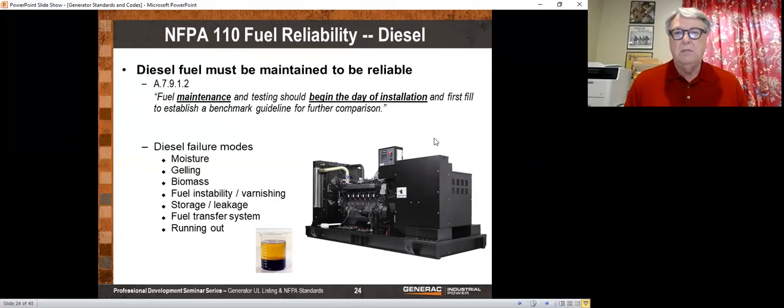So I was a little stumped, and the next day they brought up a load bank and tested it on a load bank, which is entirely linear load. And once they got above 95% load, it went unstable, the same as it had before when we were testing the VFDs. What was the problem? It was a partially clogged fuel filter. And so I was a little chagrined that I spent so much time on there and never suspected that it could just be a dirty fuel filter.